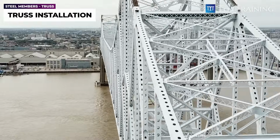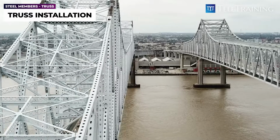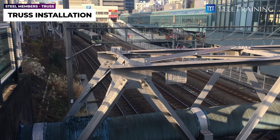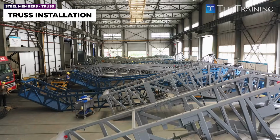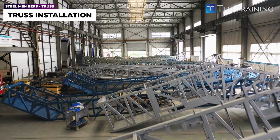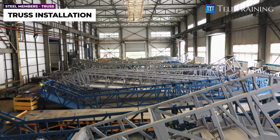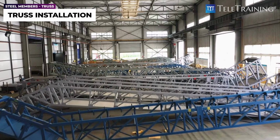In summary, trusses can span longer distances and support heavier loads than steel beams. They are also lightweight and conveniently allow services to be routed through them. While this is the case, it's important to consider the additional cost associated with their fabrication and installation when choosing between a truss and an alternative structural frame.